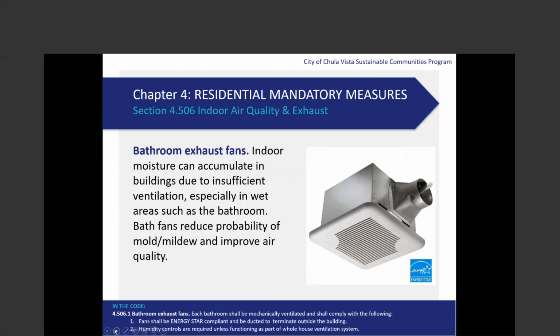To help with moisture control as well as ventilation, bathrooms must all have Energy Star exhaust fans with humidity controls. The bathroom fan must be part of a whole house ventilation system. Oh, if the bathroom fan is part of a whole house ventilation system, then humidity controls are not required, because typically they'd be running continuously. Whole house ventilation ensures fresh air is moving throughout the house, which improves overall air quality, which hopefully we've seen is important in this section. Next, please.